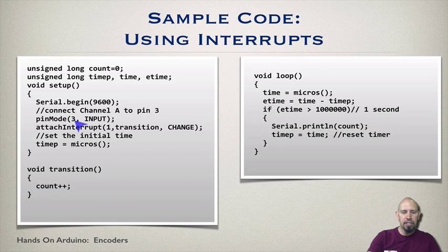If either pins 2 or 3 are not available, you cannot use the standard external interrupts. You have to use a pin change interrupt. In this case, our whole system is simple so that we don't have a lot of stuff going on. That pin is available.